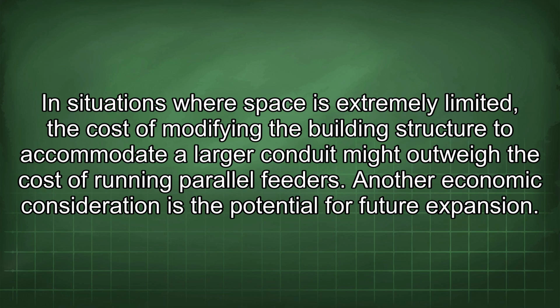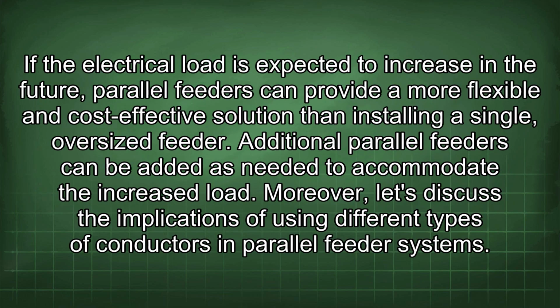Another economic consideration is the potential for future expansion. If the electrical load is expected to increase in the future, parallel feeders can provide a more flexible and cost-effective solution than installing a single, oversized feeder. Additional parallel feeders can be added as needed to accommodate the increased load.